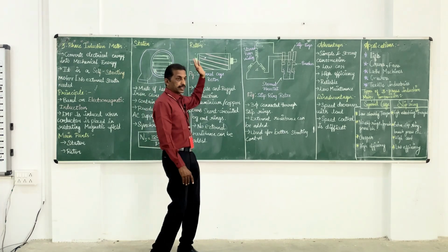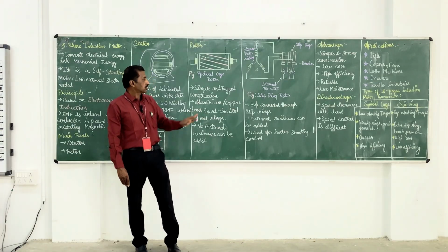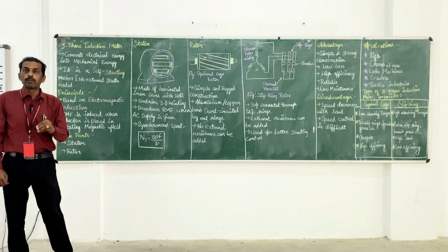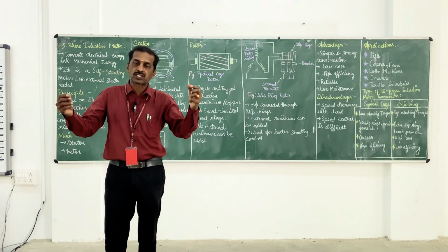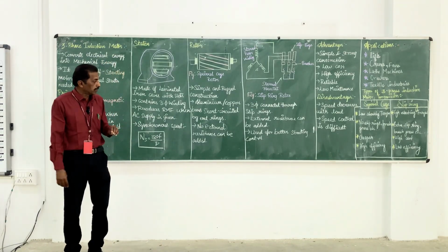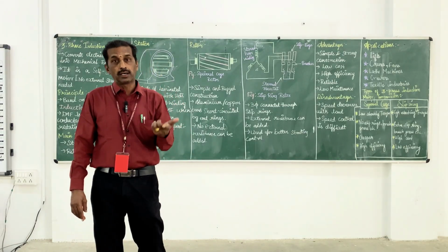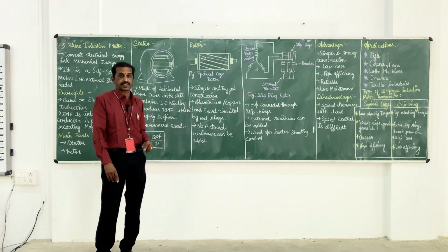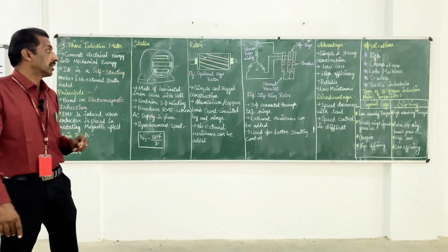This is the rotor. This rotor type is the squirrel cage induction rotor. This rotor is very simple and rugged in construction, and it is made of aluminum or copper bars. These bars are short-circuited by two end rings, but not parallel, just skewed. No external resistance can be added here. But in the other type, the slip ring induction motor, we add external resistance on the rotor side, for the purpose of increasing the starting torque.